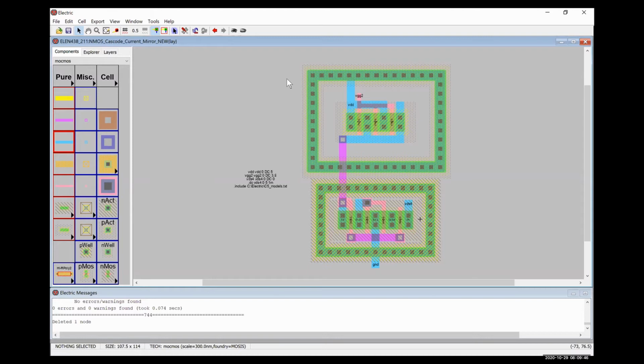So describe the errors that you're getting then. It's going to be really hard to fix if I can't see them. Just a spacing error. I was having it yesterday mainly. I was just wondering why I couldn't put them together. So it's giving you an error because you're placing 2 PMOS transistors too close together? Correct. All right, let me see if I can replicate that.